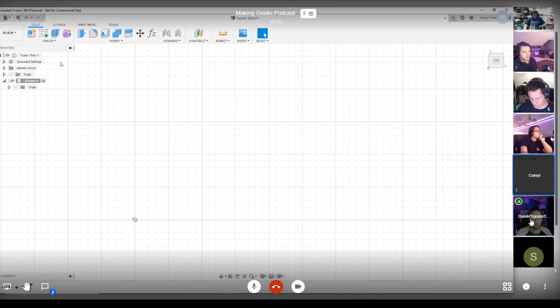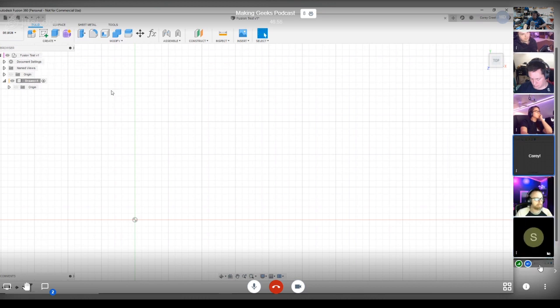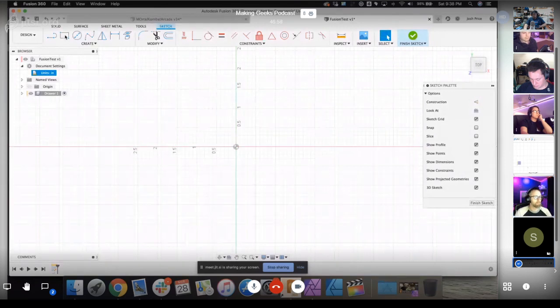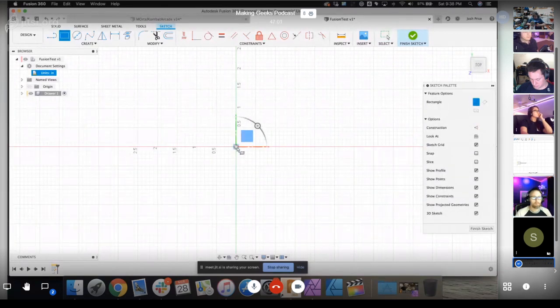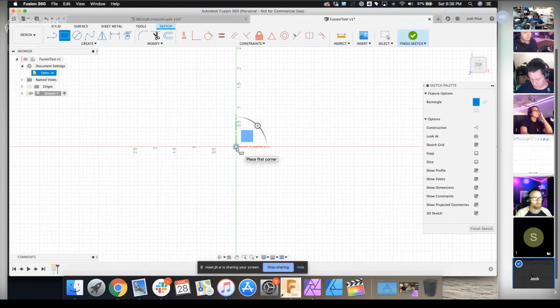Interesting. So there's a couple of ways of drawing a rectangle, and I'm going to show you what I do. Okay, so you can click on the rectangle button. You can create its starting point. And when you create a starting point, it is also creating what's called a constraint. If you look up here at the top, there are all these red icons called constraints. These are lockable relationships that you can create between sketches. When you start a sketch, you are automatically creating what's called a coincident constraint, which is this guy, meaning this will forever be locked at this point.